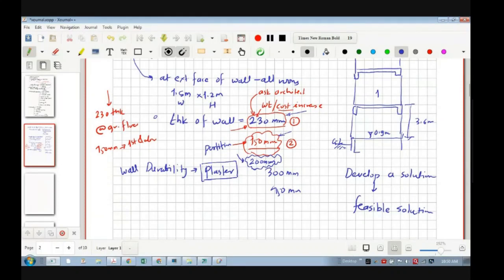जनरली ये फाउंडेशन अगर सॉफ्ट सॉइल पे रहेगा ना, ओके, let's say size is this, and this is a soft soil, matlab there is a cushioning, it is not resting on the hard soil, and then let's say yahan se gaadi ja raha hai, तो in that case ये वाइब्रेशन यहाँ से ट्रांसफर हो सकते हैं. ग्राउंड के वाइब्रेशन they will transfer to the footing and then they will transfer to the building, reverse, like earthquake we can say, kind of earthquake.